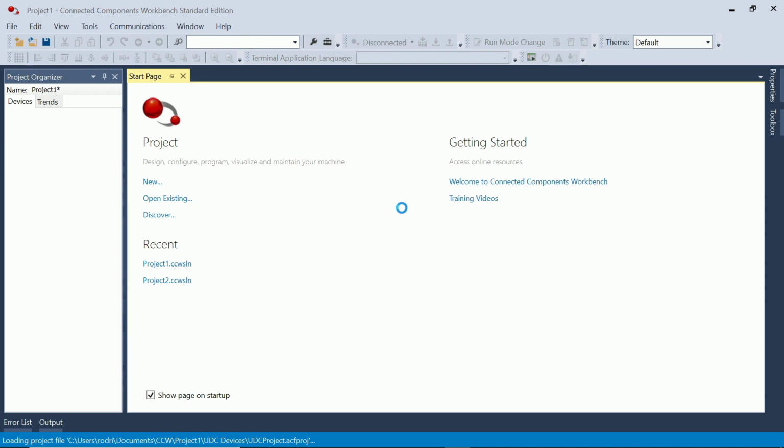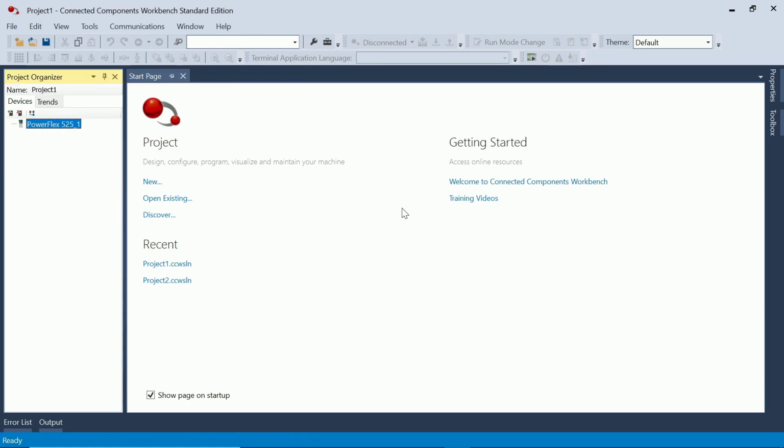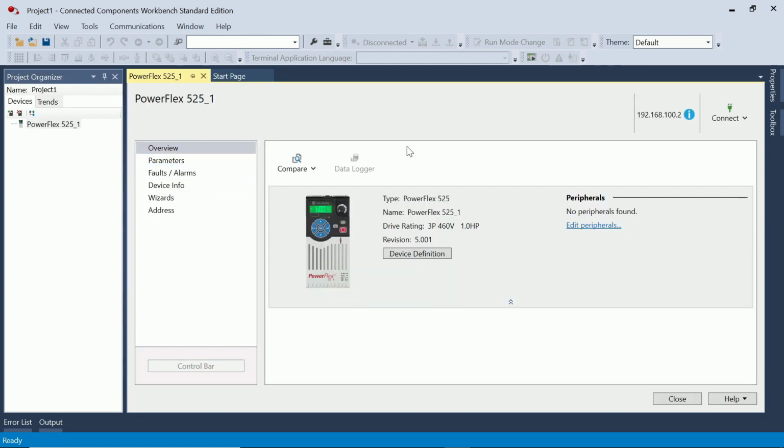and I would need to download, well, select the path, which here it is, so that I can download, and we go here to communications, select our drive, and I would have to set up my Ethernet part, so that I could then download all the information, which I already have stored for my parameters in my PowerFlex. How long is that going to take? Probably around 10 or 20 minutes or 30 minutes, but it all depends on if it's available or not, the file, because maybe it got lost.